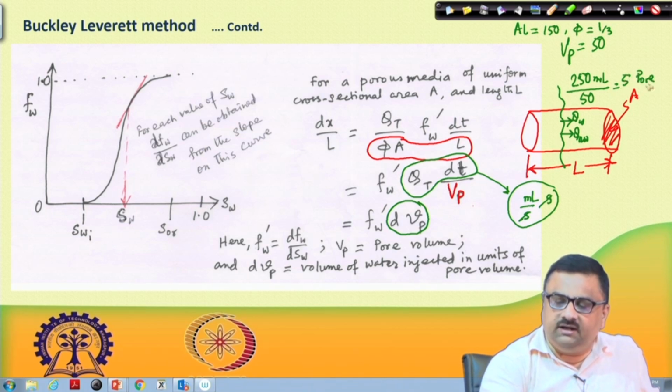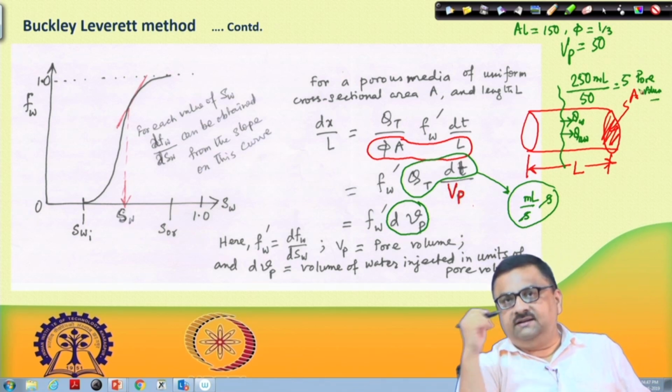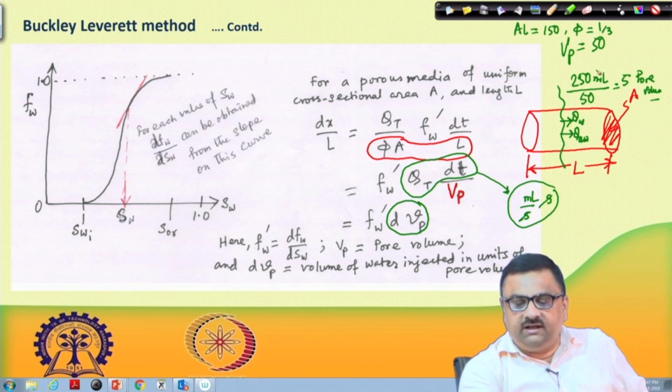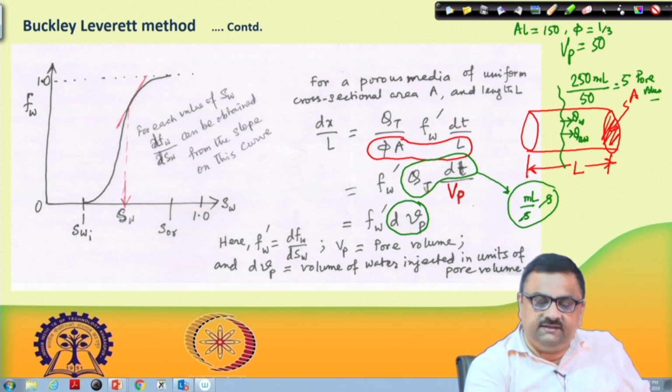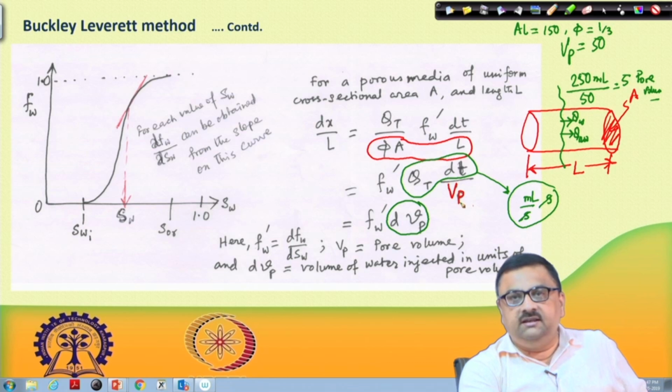That is what we had, that is what we discussed before. That pore volume would be then a unit instead of milliliter. So, then what exactly did we do? Whatever volume has flowed, we divided it by Vp, the void volume. So here also exactly the same thing: Qt multiplied by dt is the total volume that has flowed through some grid, and that divided by the Vp, which is the total void volume.